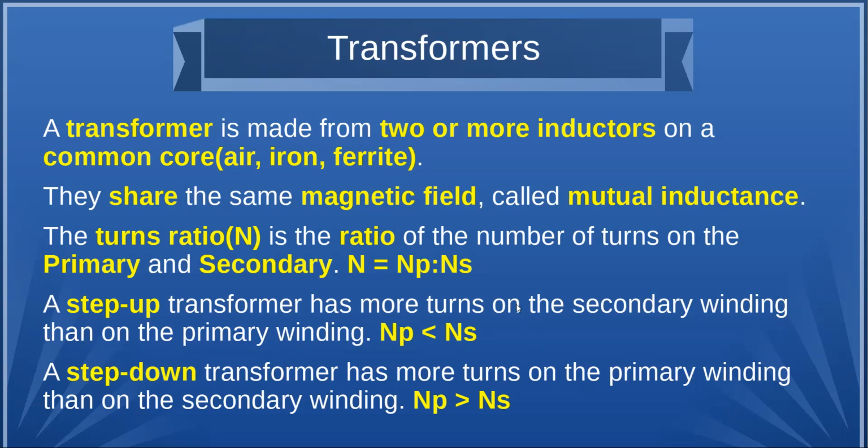However, when I do that, whatever current I have on the primary is going to be halved on the secondary, because the power into the transformer, assuming no loss, is going to be the same on the output. So whatever the input power is, the output power is going to be the same, even though the voltage and current will be different. So let's say 120 in at 100 amps, and then coming out, it would be 240 and 50 amps, if that math is right. Well, yeah, depending on what you're doing.